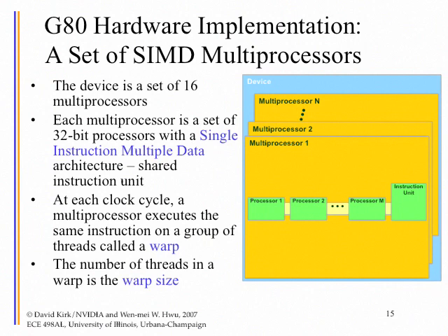What that tells you is that the hardware really breaks down the block into multiple warps, and each warp will independently use the instruction unit. Okay, that's really what's happening in the real hardware. So only when the execution diverges within the 32-thread unit do you suffer the performance penalty.